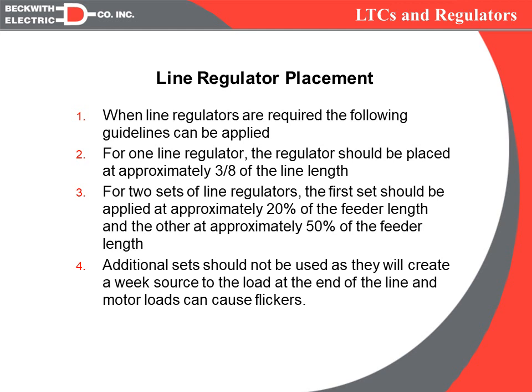But if it's an evenly balanced loaded circuit, then typically you would want the regulator about 3/8 of the way down, because that's where the halfway load point would typically be. But that's what you're looking for, is where on that circuit you anticipate the halfway load point to be. If you apply two sets of regulators, typically they'd be about 20% and 50%.